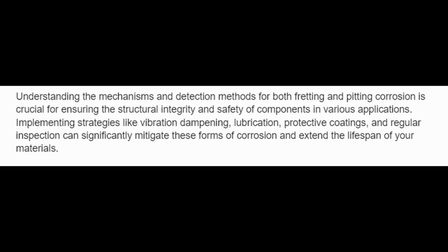Understanding the mechanisms and detection methods for both fretting and pitting corrosion is crucial for ensuring the structural integrity and safety of components in various applications. Implementing strategies like vibration dampening, lubrication, protective coatings, and regular inspection can significantly mitigate these forms of corrosion and extend the lifespan of the materials.